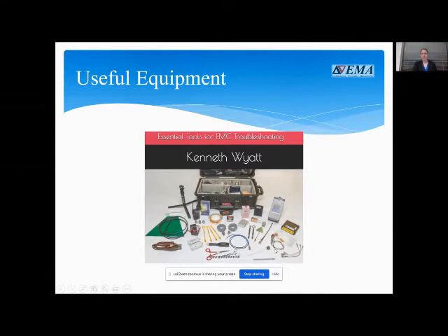This one is one of my favorites in the lower right. You see this little thing with a red button? That's a piezoelectric sparker that he probably pulled out of something like a barbecue ignition system. And the great thing about that is that every time you push that little red button, you get this nice burst of broadband noise. That can potentially give you an idea of, for instance, if you have equipment that might be susceptible to that kind of thing, or you want to know how your system is picking up noise across a broad spectrum. It's a cheap and easy thing to just carry around with you.